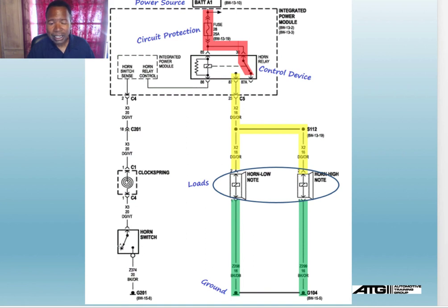But as soon as I engage this, that voltage goes through the switch to ground. Magnetism happens here. Pull the switch over, the horns go off. So again, voltage on the ground side until it's needed. Once it's needed, that 12 volts drops to near zero. So if I have an open on the ground circuit, you do not have a ground. Peace. I'm out.